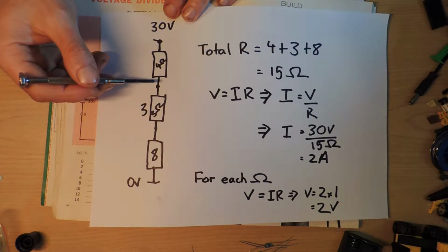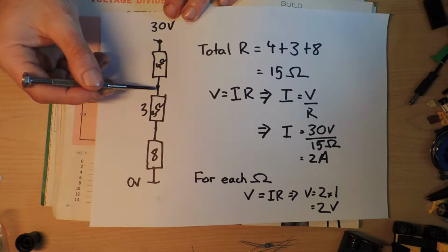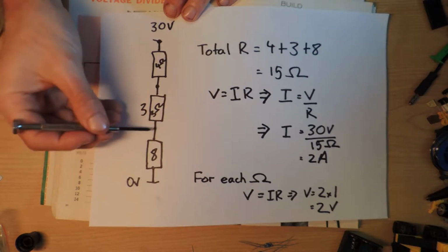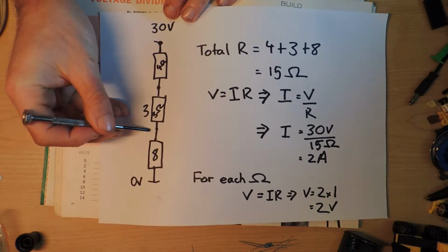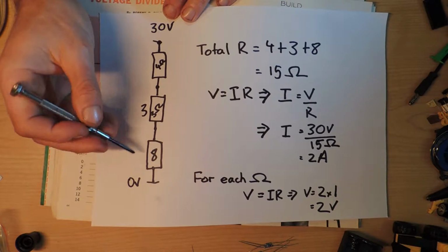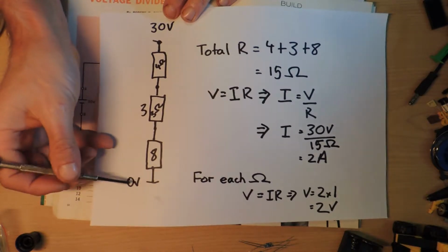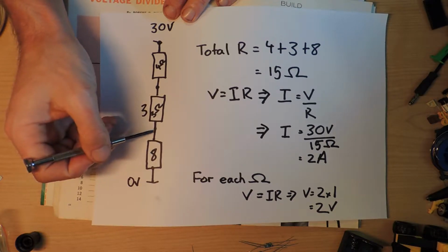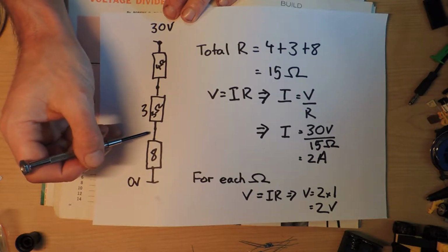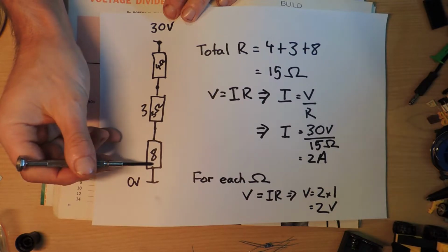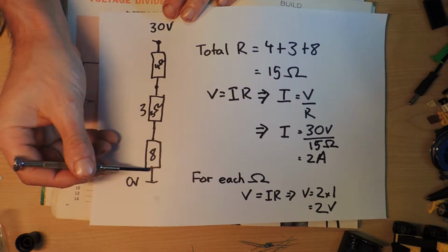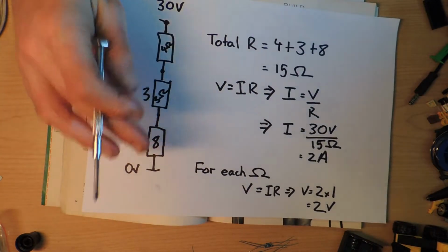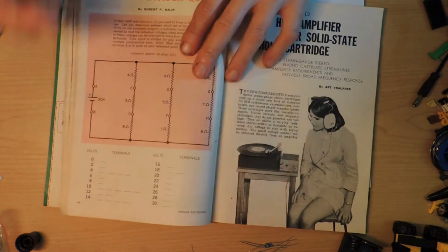So if we were at 22 now, and then we're going to use another 6 volts, 22 minus 6 will get us down to 16. So this point here will be the 16 volt point, and then to get down to the bottom, we're going to need 8. So 8 times 2 is 16, so we can check our answer here. And so we know that we have to go through 6 ohms, and that matches up. So when we go through the 6 ohm resistor, we get down to 0, which is where we're supposed to be. So we know that it all adds up. So that's how we do one line.